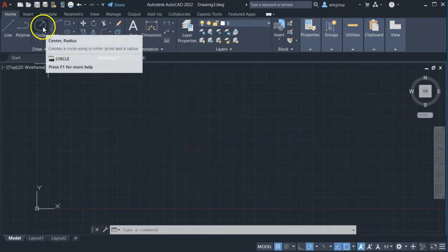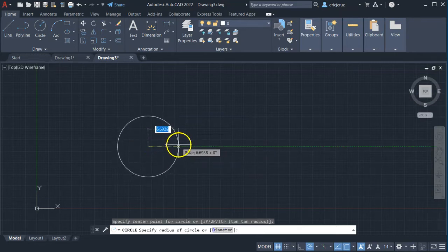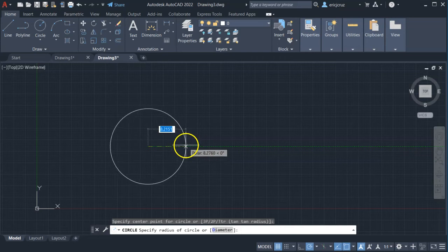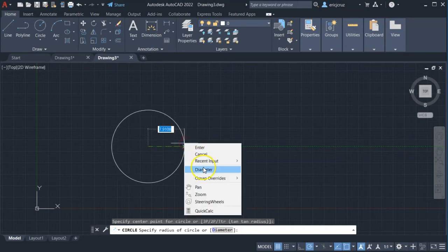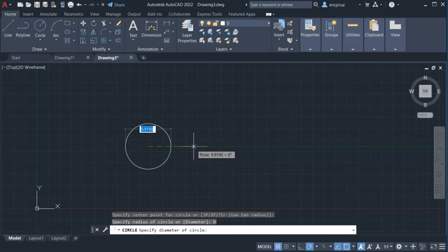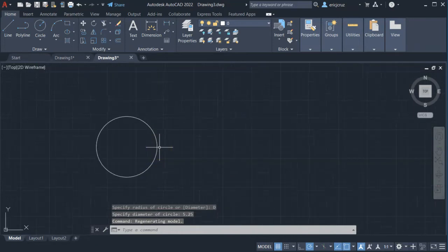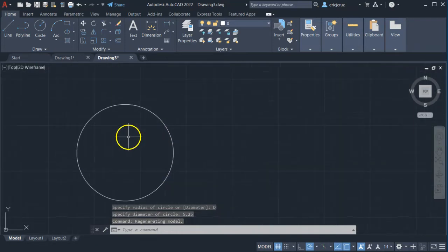So I have a circle command here, so I'm going to click circle. I'm going to click, and I'm noticing right off the bat that it's set to radius. So I'm assuming if I right click, oh, there it is, I can change it to diameter. And it looks like there are 3 main circles helping you make this part. The biggest outside circle looks like a phantom line, and that is 5 1/4. So I'm going to type in 5.25, enter. Yep, that should have made that line.